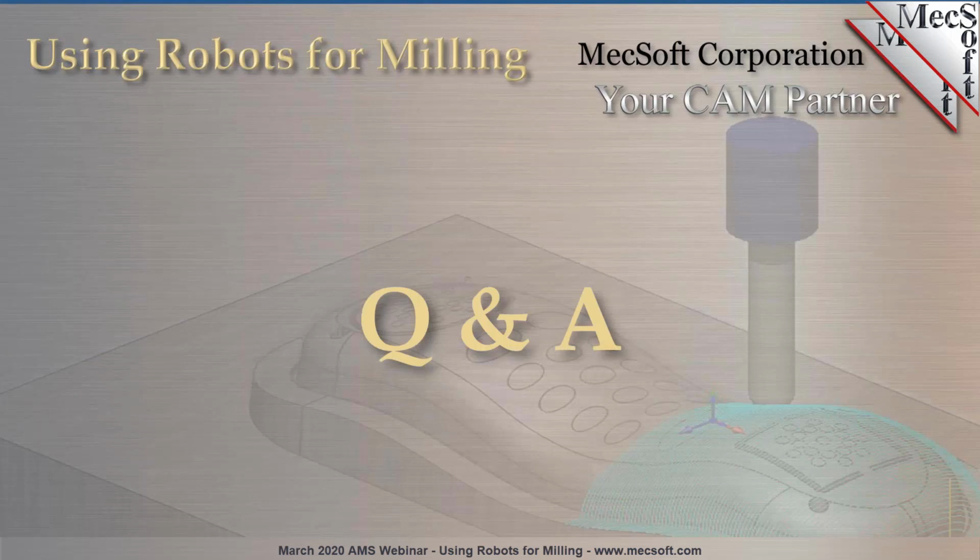We also have a network of partners that can calibrate on-site, but I would say this is the high-end calibration needs for certain customers. Because of course we know that robots are not as accurate as a CNC, not as stiff or robust. So in general, the offline programming side is enough to convert CAM programs into robot programs.